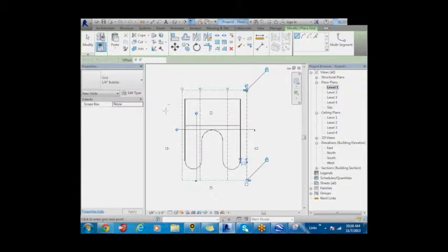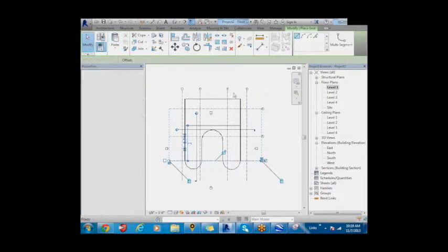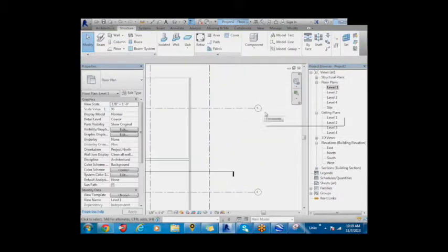Then we can do our horizontal grids. Say we had a more detailed building, we would have internal walls inside our buildings, so we would have more stuff to snap our grids to. But in this case, since we have just an outer skeleton and an outer shell, we're just going to create a few horizontal grids. Really, the goal is to put in a couple of beams and columns, so we don't really need much. Oh yes, what I should have shown, you guys probably already know this.